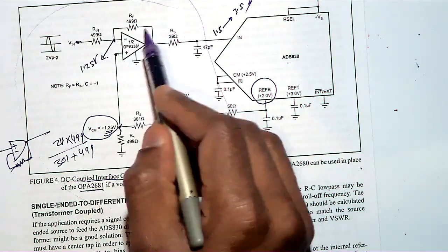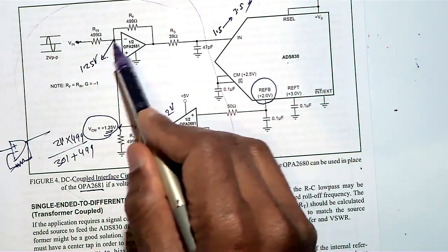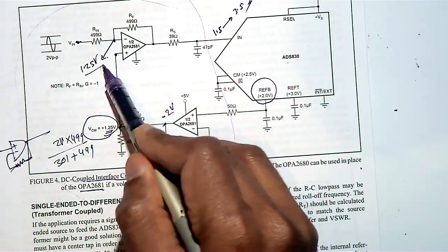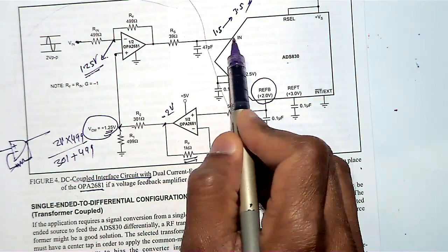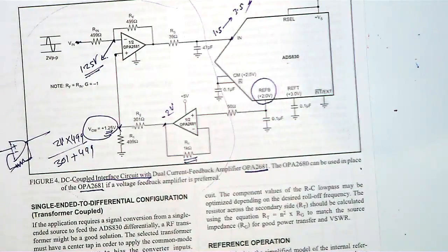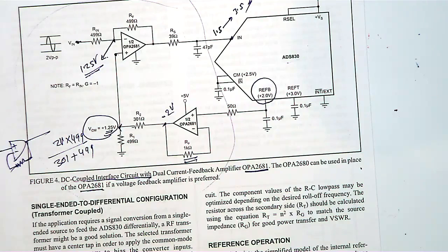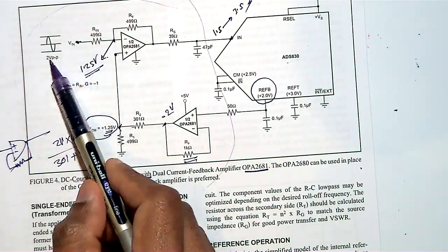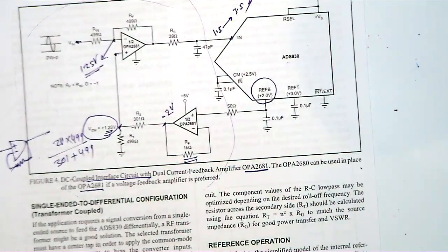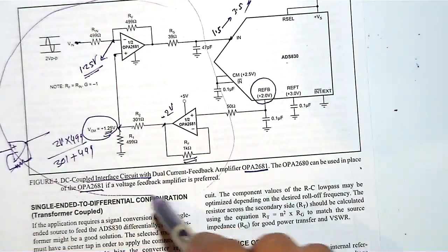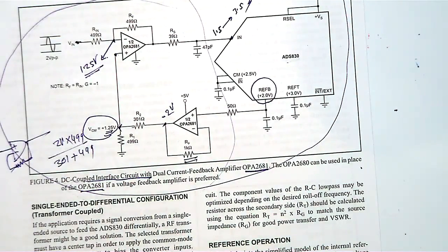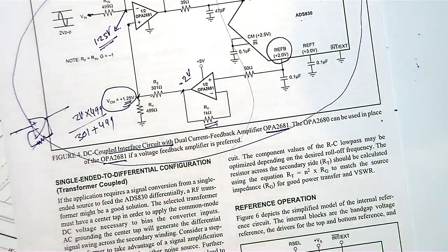And then you are getting some gain, and you have to make sure that gain is within the specification. So you already got a voltage level shifter here. And then you got a low pass filter they recommended. That's how you should be connecting, and then it is going to the ADC. Now you shifted to the required range, and you have to make sure the amplification is within that. You have to make sure that your amplifier is not amplifying above 3.5, because you already shifted your signal. Because of this, you don't have any headache. You can just copy the circuit and add it to your DSO design. That is the reason I have shown you this circuit.